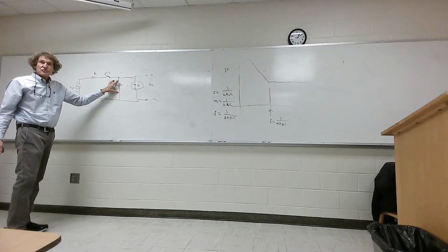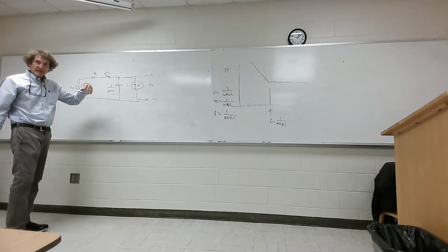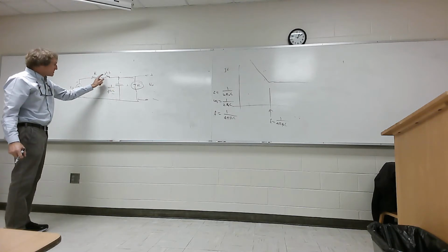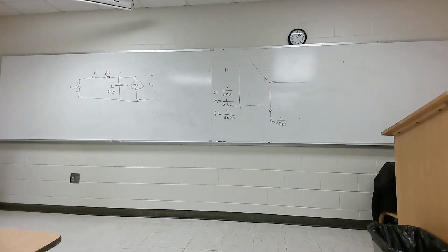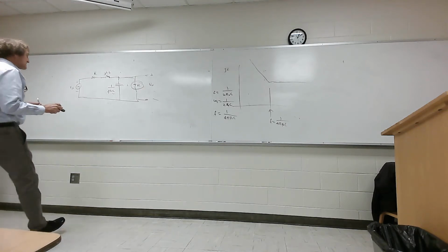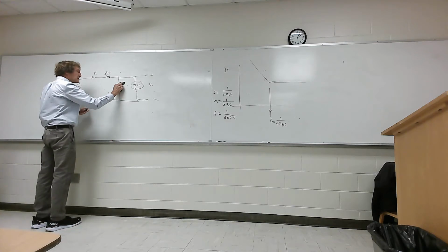But it's going to have not 20 dB, but 40 dB per decade when you do the math on this one, because you have an LC, all right? You follow me on this, guys? All right, what if I did this?